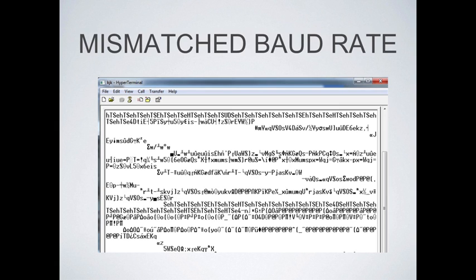So when you get something like this particular output, you want to go back and just start doing trial and error over the various standard rates that I gave you in the beginning. Like under baud rate, I said that the standard baud rates can range between like 1200, 2400, 4800, 19200, or 9600. There are various other standard rates you can try, but the more common baud rate is 9600, which is the one we were looking at before.